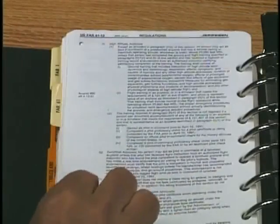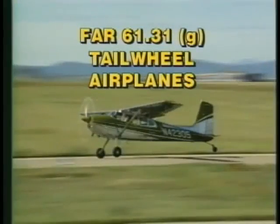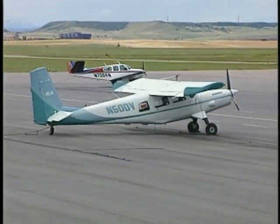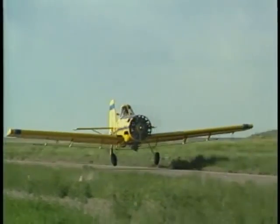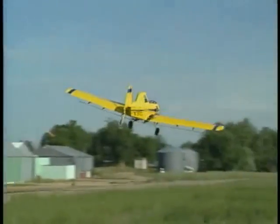Because of the unique operating characteristics of tailwheel aircraft, a specific logbook endorsement to act as PIC in a tailwheel airplane is required by FAR 61.31. Although only one logbook endorsement is required, a checkout for each make and model of tailwheel is recommended due to differences in operating characteristics for individual aircraft types.